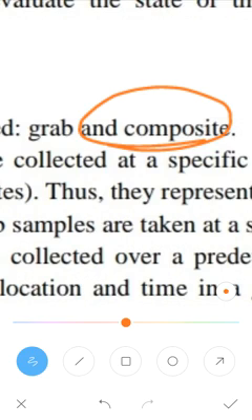Dissolved oxygen, carbon dioxide, pH and temperature changes may produce secondary changes in certain inorganic constituents such as iron, magnesium, alkalinity and hardness, and some organics. Use time-composite samples only for determining components that remain unchanged under the conditions of sample collection.